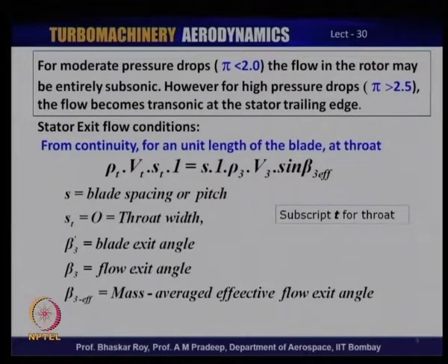The additional important parameter here is S subscript T, that is the throat width, because throat is the place where the flow actually goes sonic, and hence the throat needs to be decided very accurately, because the flow will indeed go sonic, and thereafter one has to decide whether to allow the flow to go mildly supersonic or to go back again to subsonic flow. So, location of the throat dimension is an important parameter.